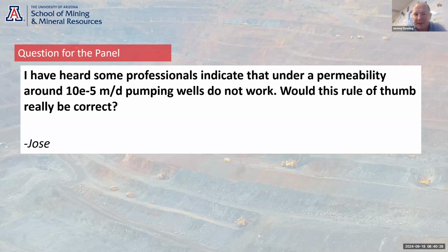You can often get a situation where the fractures near a well will initially produce good flow, and you can measure a relatively high permeability value. But once you pump the well for a sustained period, if those fractures are very limited, then the production rate and the effectiveness of the well will quickly decrease, even though you may have measured an initially higher permeability value.